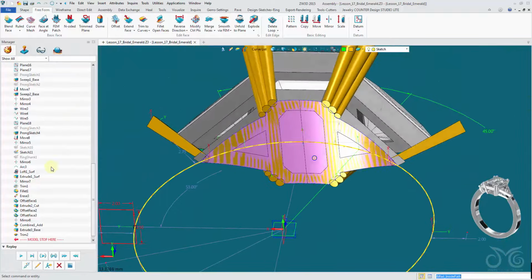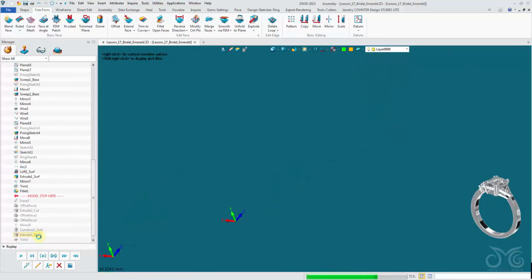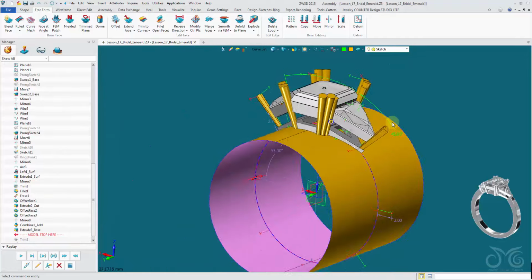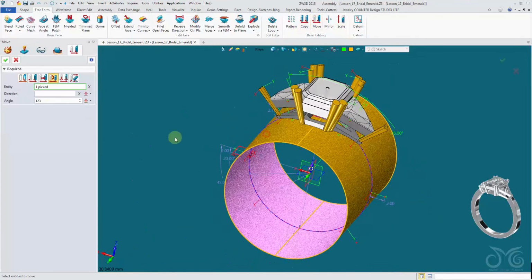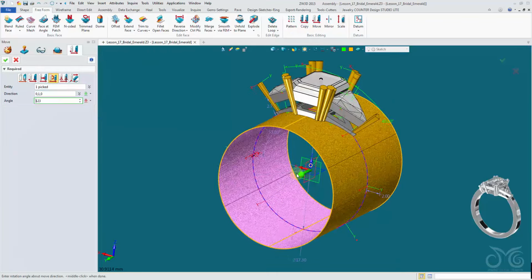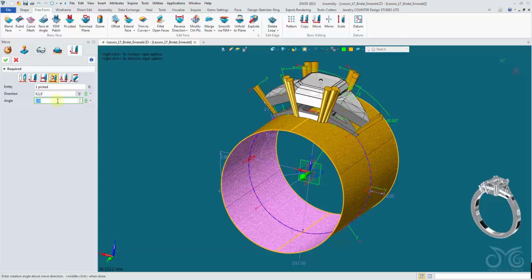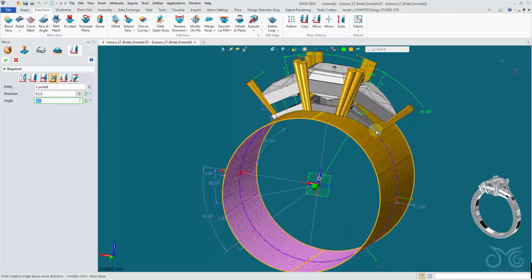Okay, so what we have to do is, prior to the trim, simply need to do a move rotate of this shape about the y-axis. It doesn't matter how much, just so long as our seam line is outside of this shape here.